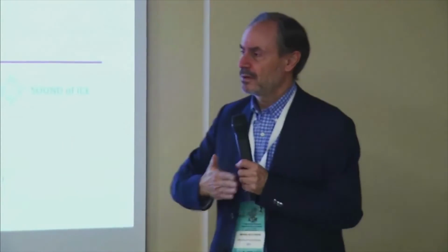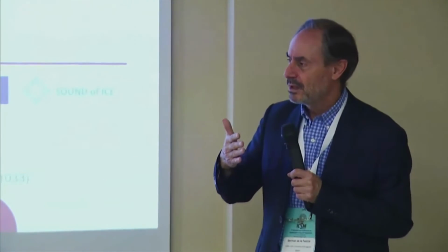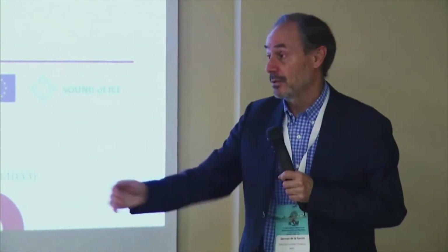This is a zone melting system, so it carries away impurities. Sometimes you incorporate impurities and you increase the concentration of impurities so much that you have a sudden crystallization of these impurities, and then you start again from zero impurities, and they build up again. So you can have a system which crystallizes or solidifies in a periodic fashion. So you don't have a uniform system, but you have a periodic system with changes in composition at certain periods.